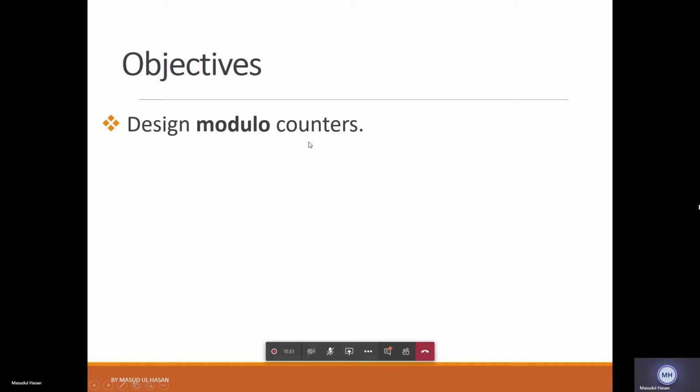Now this is cascaded 3 mod 10 counters just to make it 0 to 999. Now again, there can be one question. What is this question? If we put here, instead of counter equal 9, counter equal 99 or counter equal 999, then we can get those counts. Yes, it will do that job, but we cannot display on a 7-segment display.